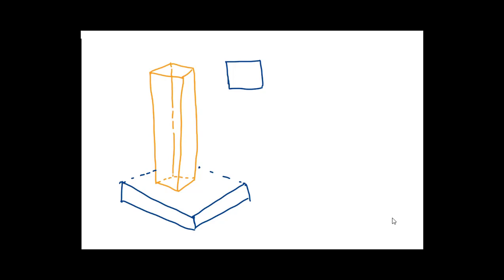It will have two dimensions. One is depth or edge, and another one is breadth. Along with that we need one more, that is the height of the column from the footing up to the height for which we are willing to find the shuttering quantity. Let us say that as L or H. If I consider this height as H, I will consider another dimension as D. B will be fixed.